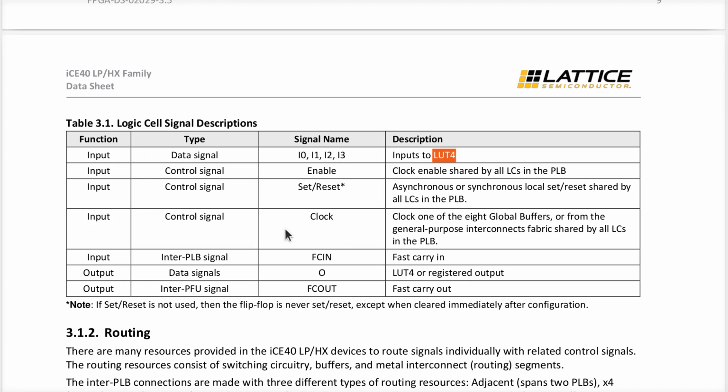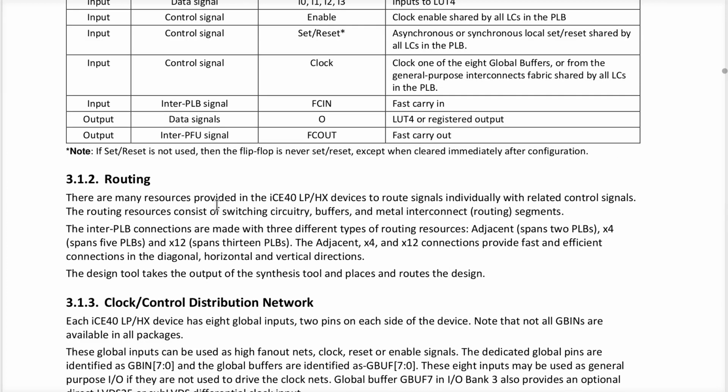That's why, by the way, you use this hardware description language. The whole point of using a compiler is to be able to write in a higher level language and then have it output. You can actually go in and see the output, and it says, I'm going to create a whole bunch of LUT4s, and each LUT4 will be interconnected like so in order to have the functionality that represents the kind of code that I'm going to write for a module, for example. Now, in order to connect them together, you go through this routing matrix.